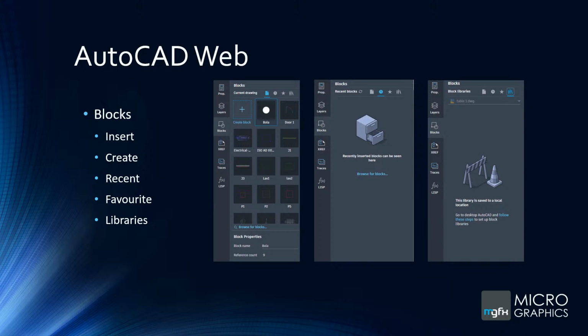Blocks. So this is fantastic because think about it. When you normally create a drawing, are you always creating it from scratch? Probably not. I would say about 70-80% of the time, you've already created your library components because that's the best way to draw with AutoCAD. Save it as a block and then bring it in and position it, and there you've got your end drawing. Then you just have to go and dimension it.